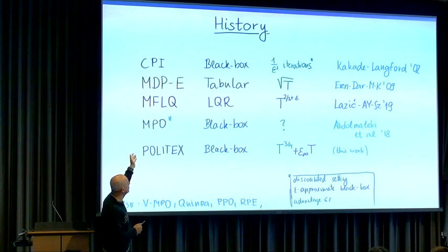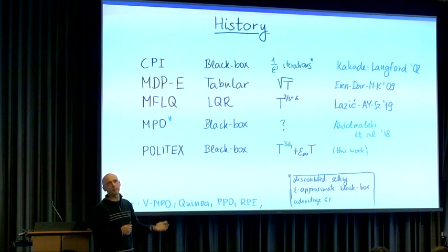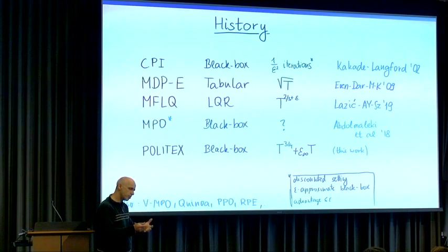We noticed that you can do this when we were working on LQR problems, and we wanted to get model-free algorithms to work. There is a little difference, because the loss functions, under nice assumptions about the system, are strongly convex. So you don't have to use Boltzmann exploration or any exponential weighting. You can just follow the leader, and you get better regret bounds there because the losses are strongly convex. So you can get this T to the 2/3 regret.